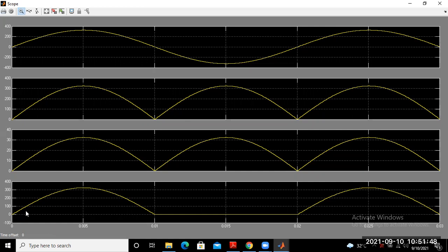But still we have to check the connection of the voltmeter across the diode 1 and 2. Because whenever diode 1 and 2 are in forward bias, that means in conduction mode, the voltage from 0 to pi becomes 0. But here it is showing a voltage. That means we have to check the connection of the voltage across the diodes D1 and D2.